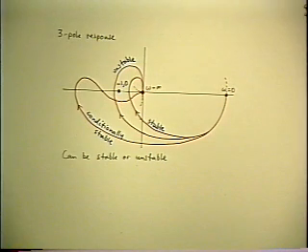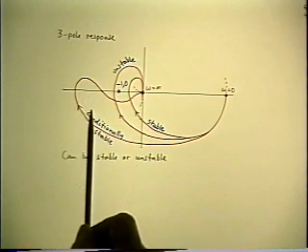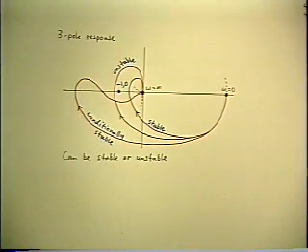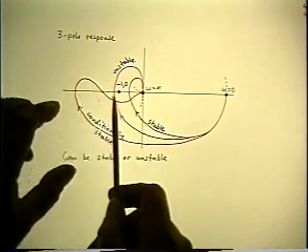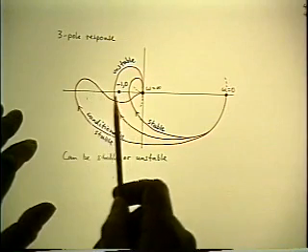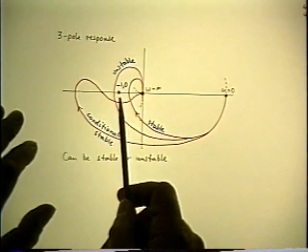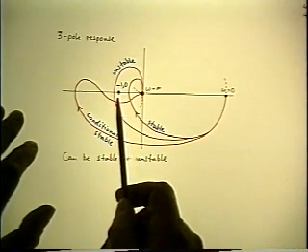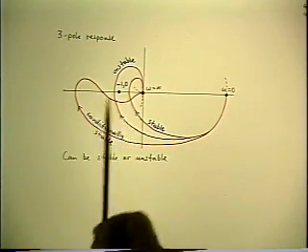And that's only one of the possibilities, because suppose you survived that and it did finally come up to the conditionally stable system and everything is fine, but then someone comes along and hits the output with an overload. Again, something saturates, cuts off, the gain drops. And the contour contracts. And again, it's going to be very difficult to ensure that it doesn't contract in such a way that it could go unstable again during the overload. And you could also be unlucky and it could get stuck in the overload condition. Even if you remove the overload, it may not recover because it's already oscillating and going nonlinear.